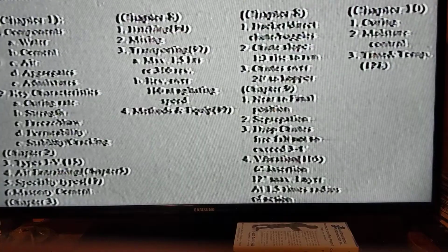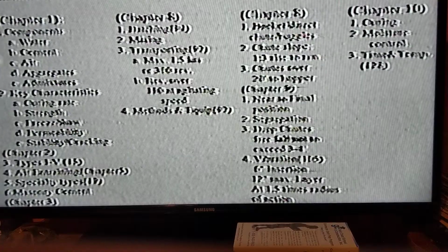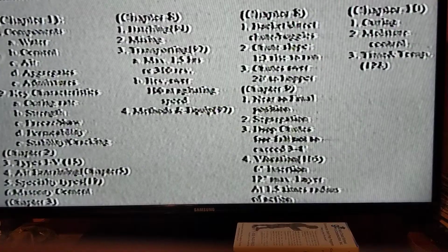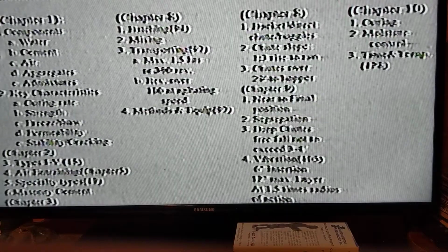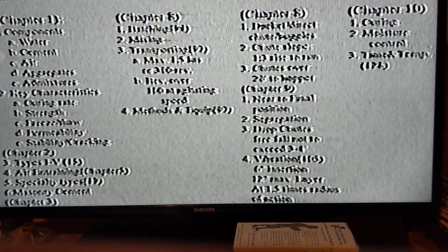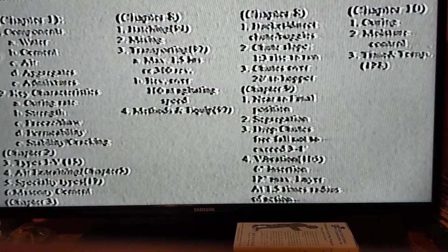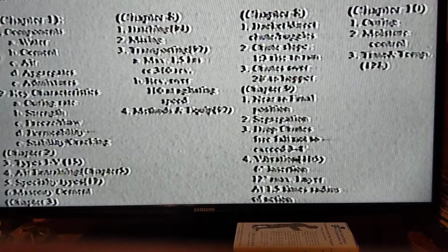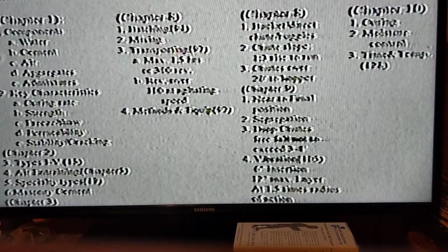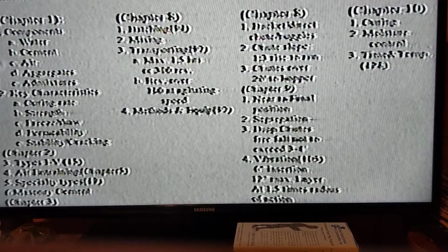Water is both a friend and an enemy to concrete. Water is necessary to create hydration. The chemical process of hydration is the process of the milkshake hardening. Concrete takes a long time to harden, approximately 80 years. So that slab you poured a year ago is still getting harder and harder. It's still hydrating, and this process will continue for a long time. If you don't believe it, go to an older slab and hit it with a hammer, and then try that with a new slab. The older slab, you're going to hurt your wrist.